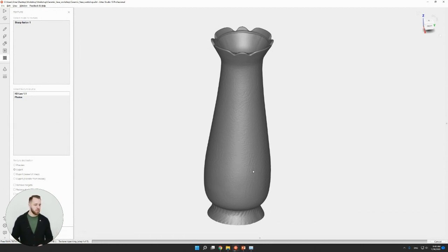So there is virtually no use for combining your scanner's texture with the texture from your pictures. Well, arguably the only benefit could be that if you missed a large area with a camera, then it will most definitely be covered in your original scans. But then again, it's probably easier to take a few more shots and re-import the texture, rerun registration, and reapply it than using both.